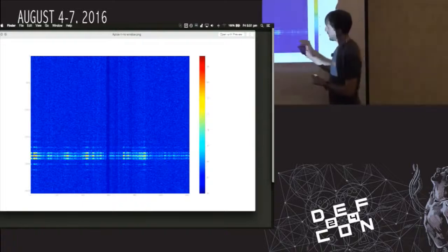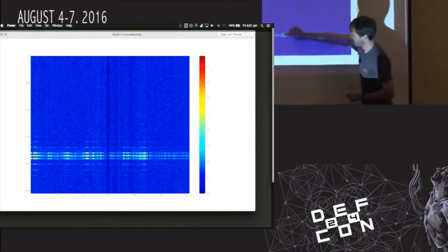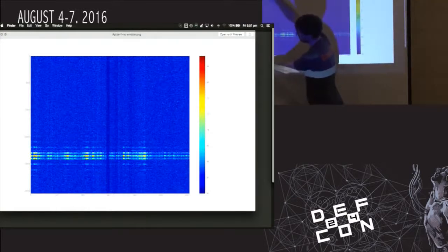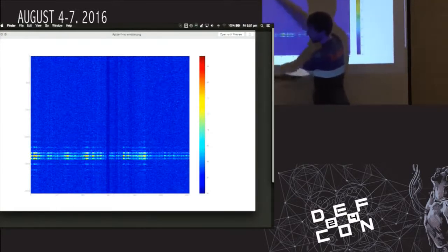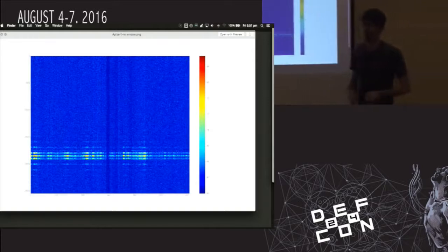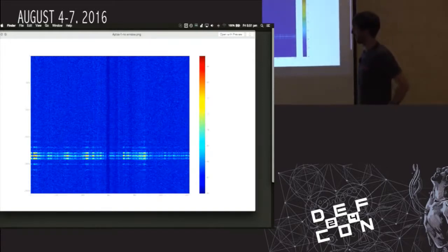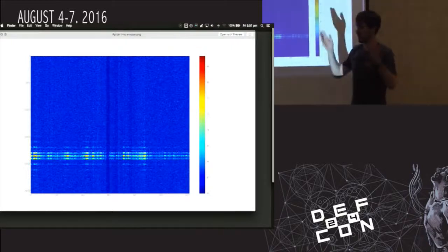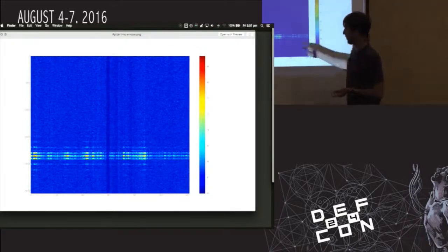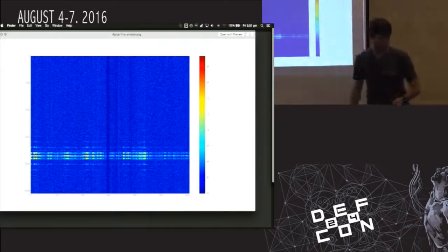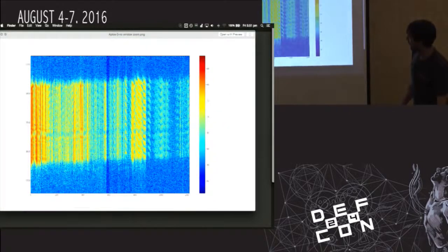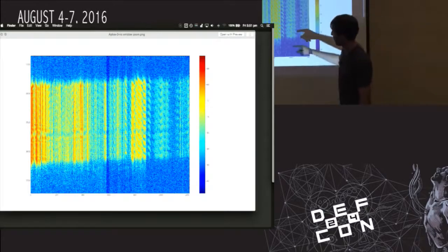And what we're interested in is what's going on in this band right here, because if you consider the speed of light and the distance that it would traverse over the length of a chirp, we're talking multiple times around the world and then some. We're only interested in stuff that's close and effectively up to the ionosphere, which can be a virtual range of a couple of thousand kilometers. So that's just in this very small band. And if you zoom in there, then it ends up looking a little bit like this. I'll show you another plot in a minute.